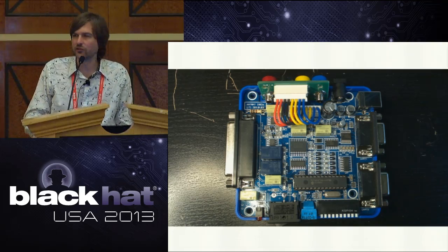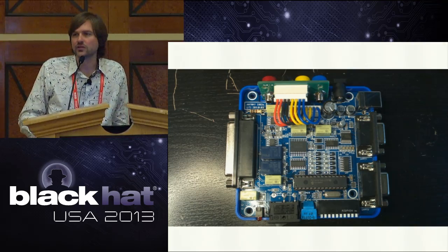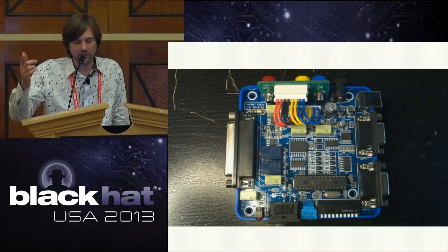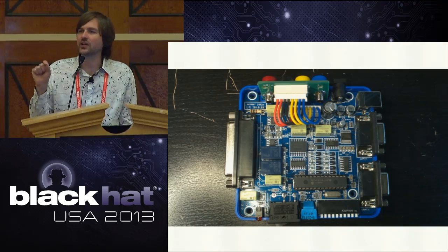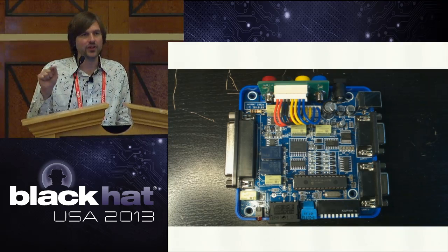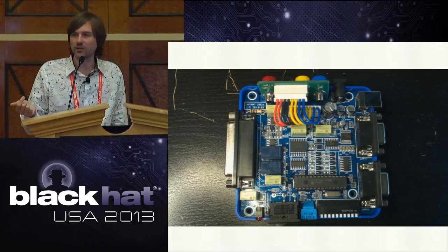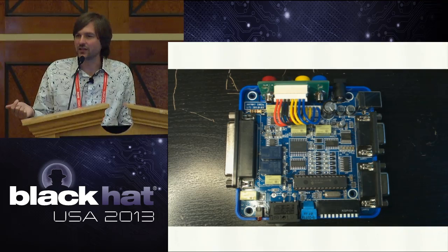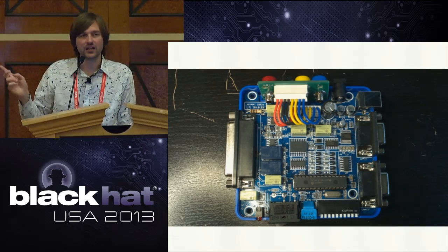There's a grid of surface mount parts that includes a bunch of fixed resistors. You can't read it from there, but with my magnifying glass I could read the values off those resistors. And sure enough, there were several values that corresponded to the table of values commonly used for those multiplexer ICs. Interestingly, 150 kiloohm is not in this.